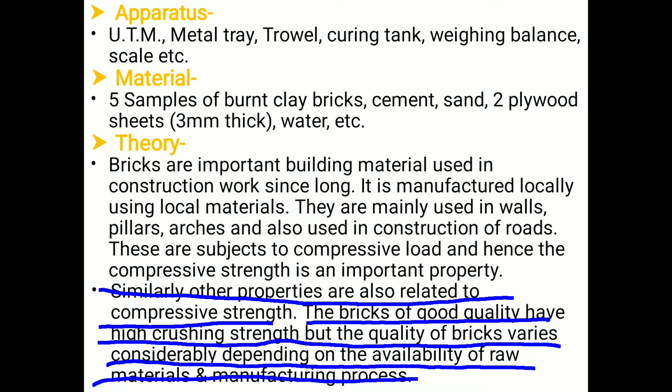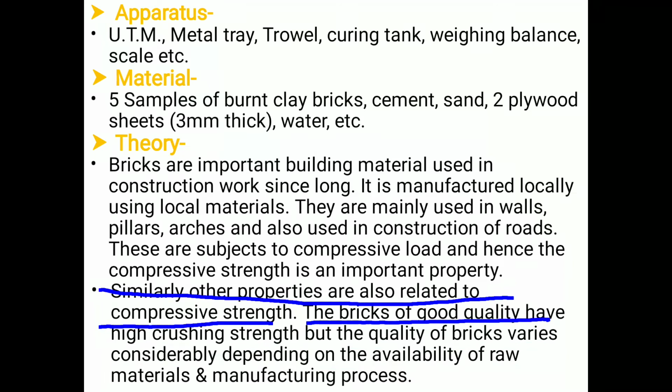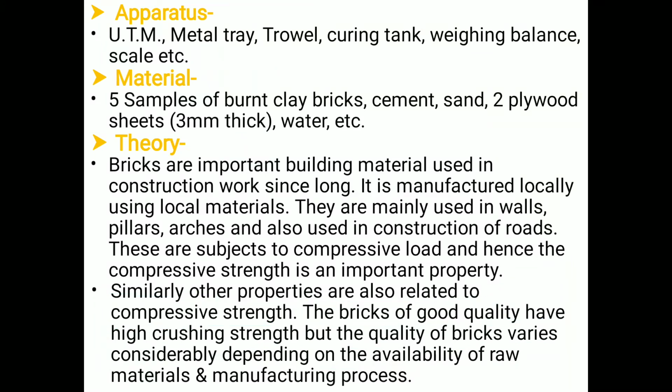The load required to crush the brick is more as compared to a lower quality brick, and it varies depending upon the availability of raw material, meaning the clay, and the manufacturing process. So remember that the compressive strength of the brick depends upon the type of the clay, the burning of the brick, and also the manufacturing process.